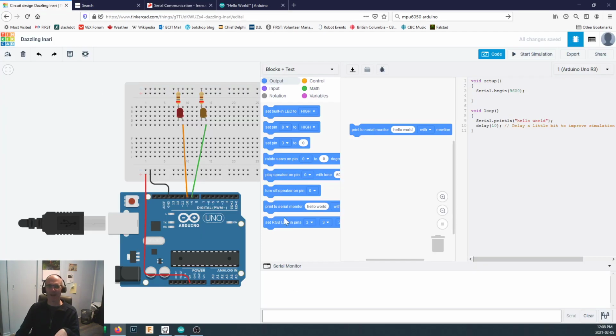Let's come back to our circuit right here and take a look at what's happening. Now, when you type this in, I just want to point out that there is a capital at the beginning of Serial and not a capital at the beginning of begin. Arduino cares about capitalization. So drag and drop takes care of it for you, but if you fail to capitalize something, you'll have a problem.